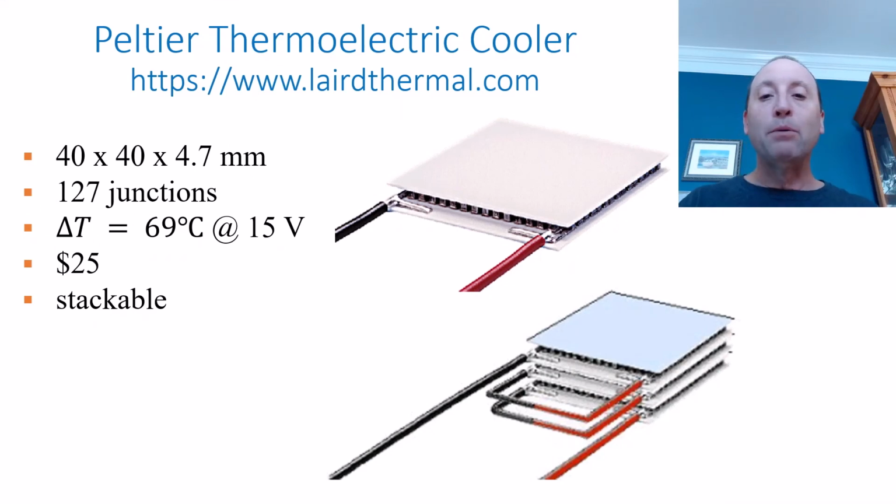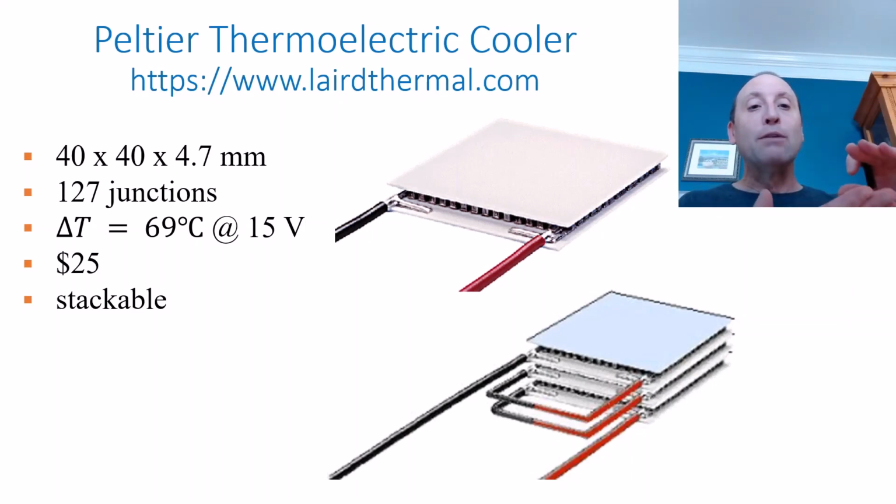So here's just one example of one of these Peltier devices that costs about $25. It actually consists of 127 junctions between the dissimilar materials, and at 15 volts of input, will create about a 70 degrees Celsius temperature difference between one side and the other. You can stack these up, so you can have the cold side of one be the hot side of the other, and even get a greater delta T for the voltage that you put in.